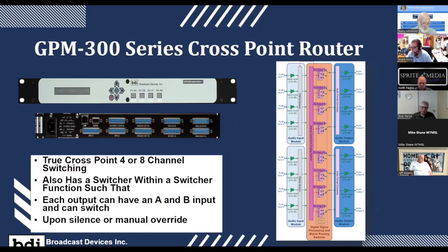So what we did there is you set up your A inputs for your program outputs, whatever they are, they're going to feed your transmitters, and you use the same B input across all those inputs, and that's your EAS generator output. And then we did one more thing. We added a serial interface, a direct serial interface between both the Sage alerting units and the Digital Alert Systems DASDEC units. They use a common serial protocol.